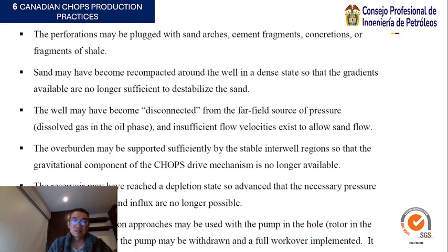In this case, various injection approaches may be used with the pump in the hole, rotor in stator, or rotor backed out. Or the pump may be withdrawn and a full workover implemented.